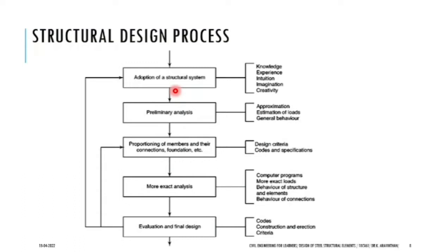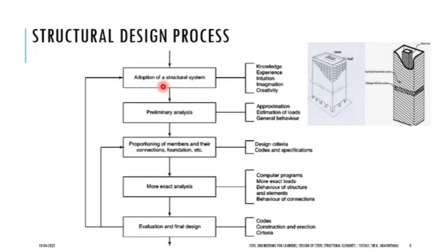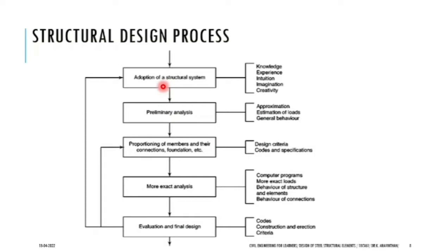If you are going far beyond that, you need shear walls. Shear walls are the construction built in apartment houses. Without shear walls, practically no apartments are built. And if you are going beyond that, for 12 floors and up to 30 floors, you need core walls. Core walls are a different structure where the walls are constructed using steel and concreted after that, and the reinforced concrete walls will be in the center, and the outer walls will be there as you see everywhere, the brick walls. These are all called structural systems.